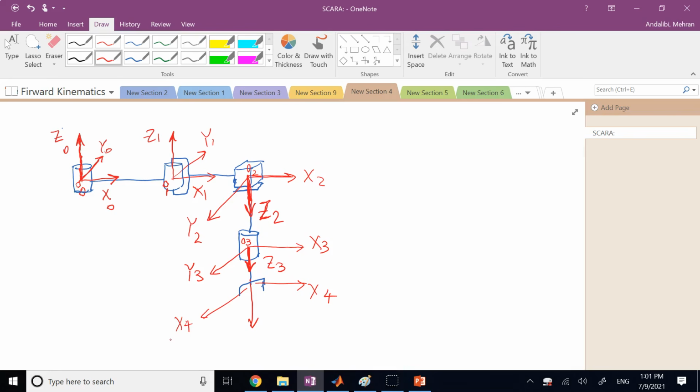And so if I go with this case, say this is X4 and this is Z4 and then this is Y4, that gives me the simplest scenario possible, because from frame 3 to frame 4 there is no rotation, so that makes it very convenient. Or I might say, well, no, this is what I do. I would call this one X4, perpendicular to Z3, yes. Does it intersect it? Yes, because if you continue Z3 and if you continue X4, they would intersect at this point.